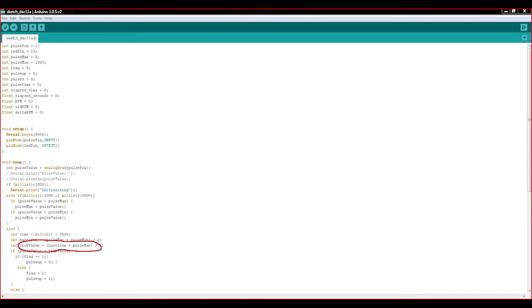Tick value sets the value above which a heartbeat will be counted. Pulse up is a software flag that tells code to increase the number of total pulses counted. Pulses keeps track of the number of pulses since code has started running.